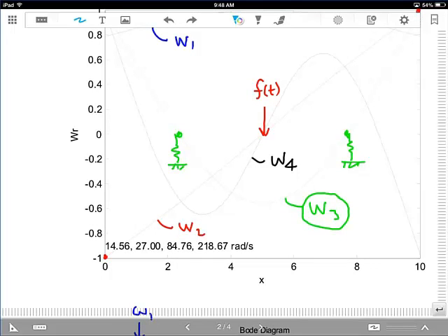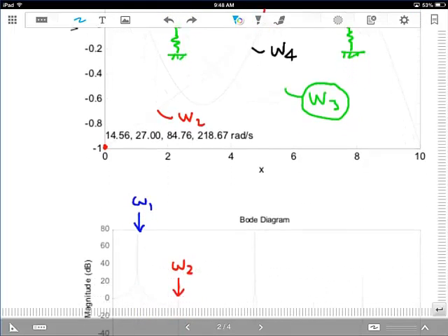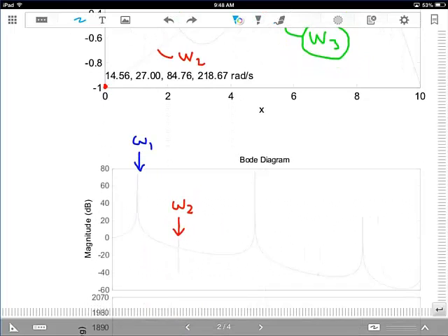So what that means is you can't excite that mode with a force at the center. Now the reason we see a sort of peak, it's almost a perfect pole zero cancellation, but not quite. Why is it not perfect? Because the theory says there should be nothing there, so it should be a perfect cancellation. But with finite elements, you can't get that exactly in the middle, and there's some spillover effect of the discretization, and so therefore you see a little thing like that.